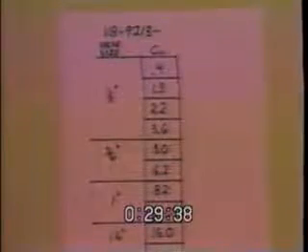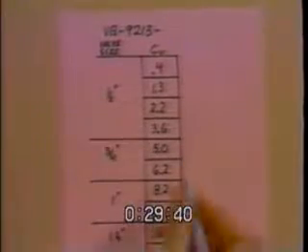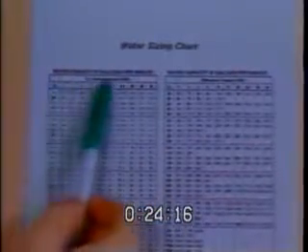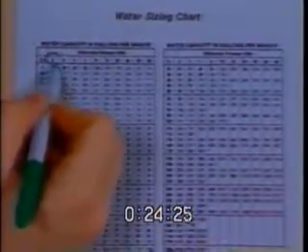how close you can come, finding an actual CV. The other was a calculated CV. In our examples for the steam valve, the method here is the chart. And again, sizing the water valve, we can take a look at this and see that on the top we have the differential pressure. This is the pressure drop. In our example, using that same one, we wanted a pressure drop of 2.